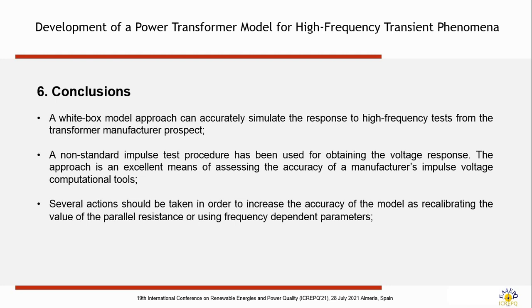Anyway, obviously the results can be improved, and there are several actions we can take, as I said before: reviewing the capacitance calculation, ideally making some parameters frequency dependent, or recalibrating the value of the parallel resistance, which governs the decay of the wave.